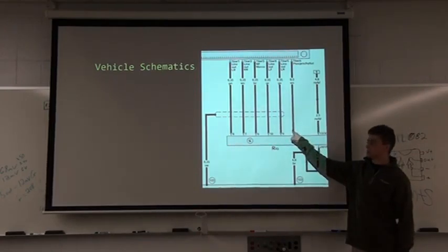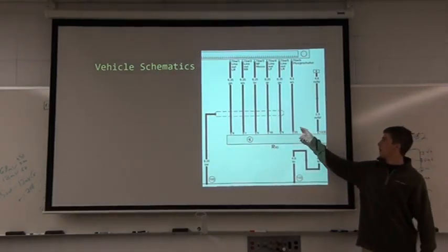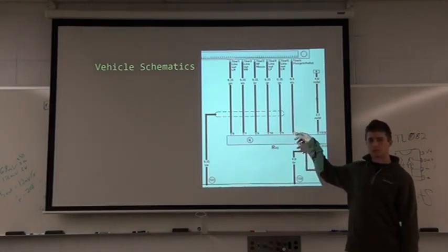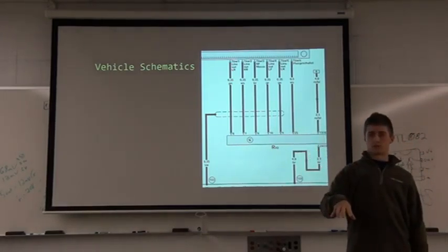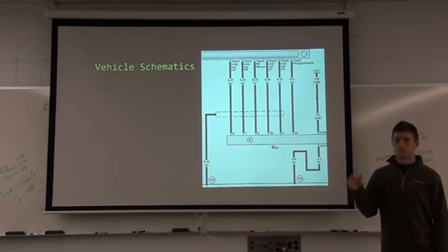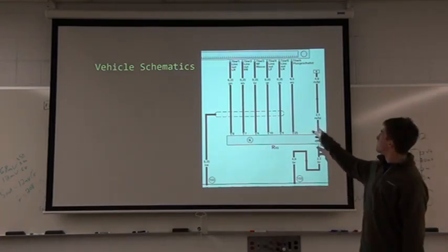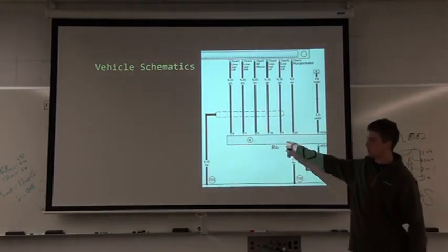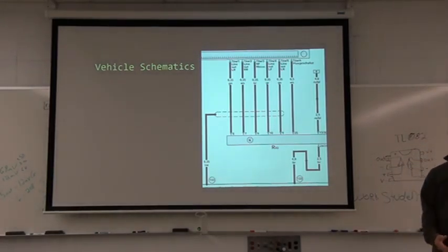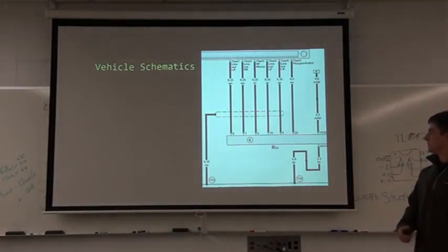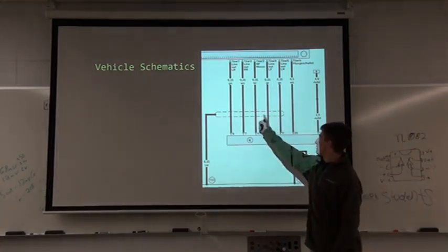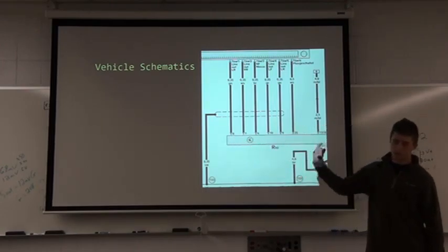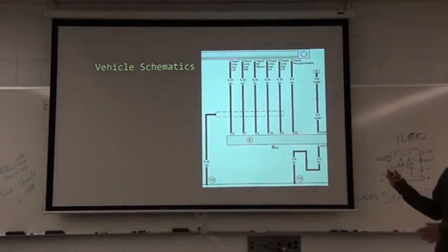This is the switched power for the powered amplifier. I'm going to utilize this wire to turn on my board, so that when the radio turns on, my board turns on, and when the radio turns off, my board turns off. By having these wires going straight to the amplifier, as I said before, it allows me to just switch the signals to the amplifier. This is just grounding on these signal lines, because there's a lot of excess noise in the vehicle wiring harness.